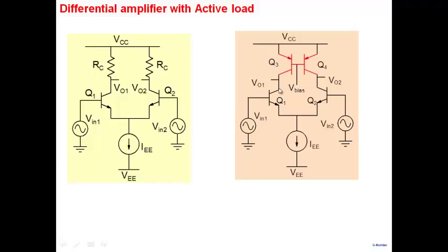Remember, the only supply voltages that enter your IC are VCC and VE. These will be like two pins in an IC, and you will have VCC and VE going here. So this bias voltage that you see here, you have to generate it from VCC and VE. So you'll have to use some kind of resistors or whatever in order to generate V bias here.